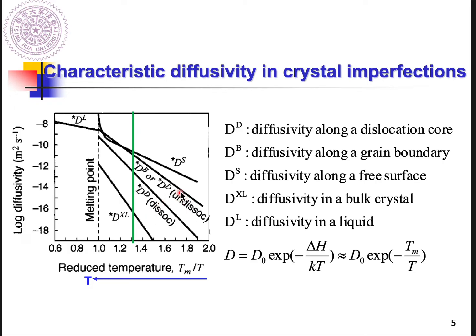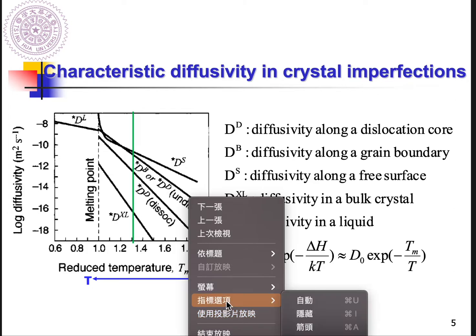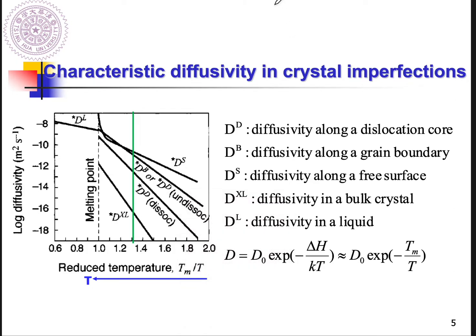As this is the larger dislocation, that tells you the lattice distortion energy must be higher than this one. So based on the energy being higher, you can expect that the energy barrier will be what? Smaller.